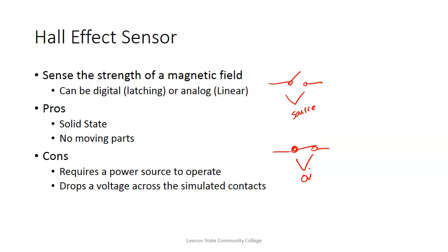And there'll be a question on the test, by the way: how much voltage should you measure across a closed switch with 120 volts applied? Somebody in this class is going to say 120 volts, and of course, that's wrong, so you'll miss that one. I've told y'all the answer because that's very important to know. Not knowing that could get a person killed. You could go to a light switch and measure across it, it measures 0 volts, and you say, well, no voltage there, and then you stick your hand in there, and then we talk about you in the past tense.